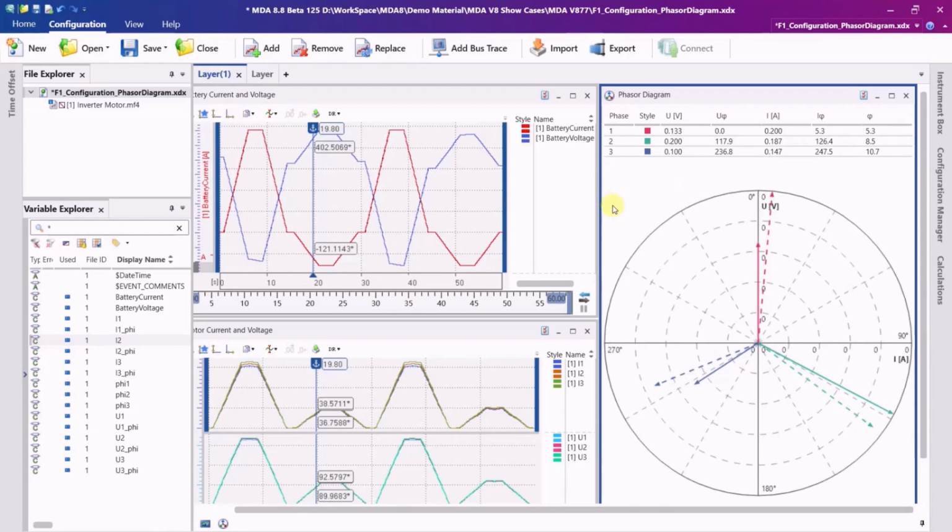At the top of the instrument, there is a summary area displaying key values including voltage, current, phase, and other important electrical characteristics. The bottom section features a graphical view that simultaneously illustrates both the magnitude and phase angle between voltage and current, making it easy to understand their behavior. The solid line represents the voltage value and the dotted line represents the current value.